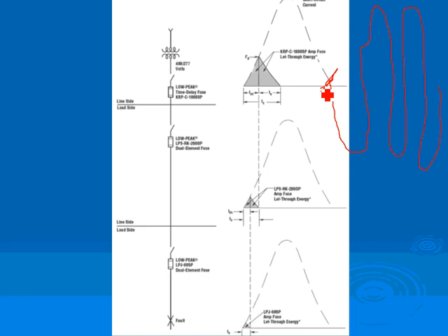The only way you can reach type 2 protection on a power system, my understanding is, is if you have low peak current limiting fuses, because it will not only trip, but it will trip fast. That will limit the amount of energy. That's why a lot of electronic equipment has, after your circuit breaker, a couple of fuses to protect it upon the existence of a short circuit. You don't burn them.